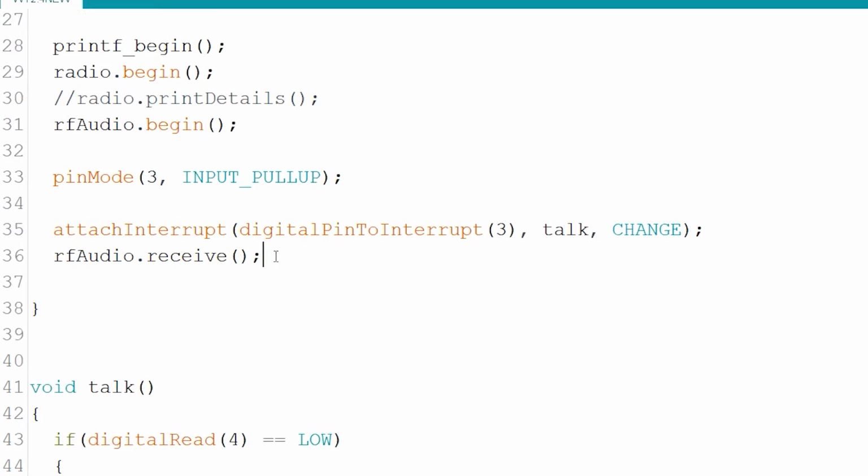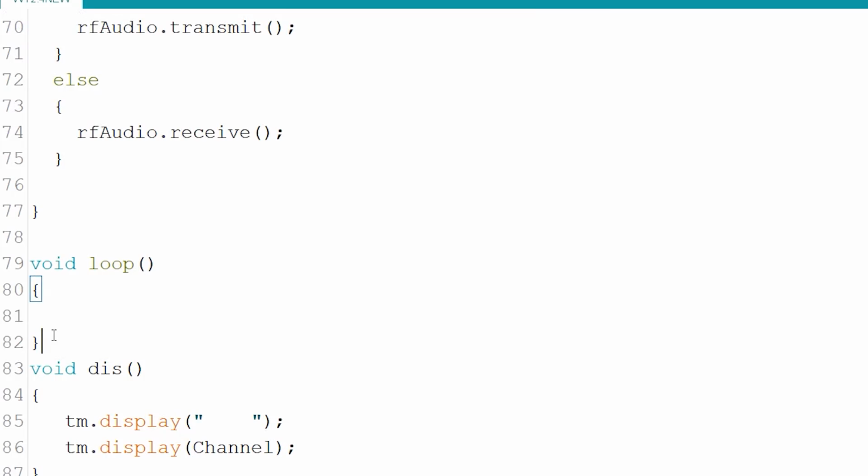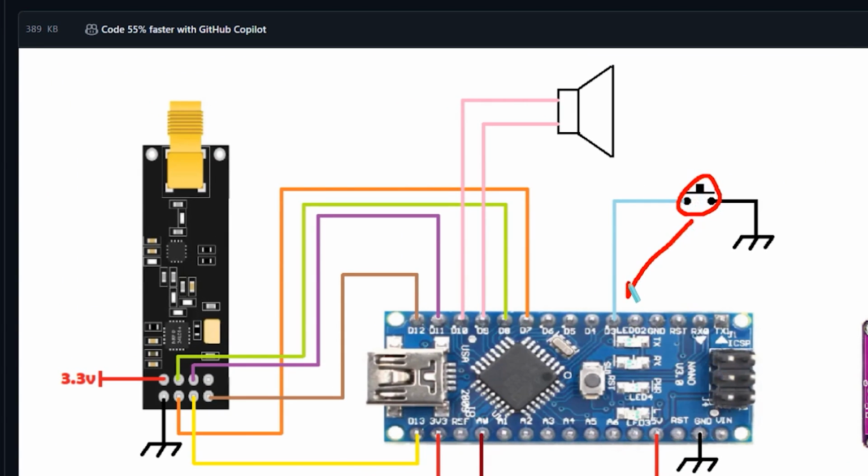at all. The reason for this is that the program is just listening at speed. Listening to the sender is done using a function that we do not have access to. As a result, the program never enters the main loop and no code can be written inside it. The good news is that this circuit has a microswitch that changes the state from receiver to transmitter, which is connected to the interrupt pin of the microcontroller.